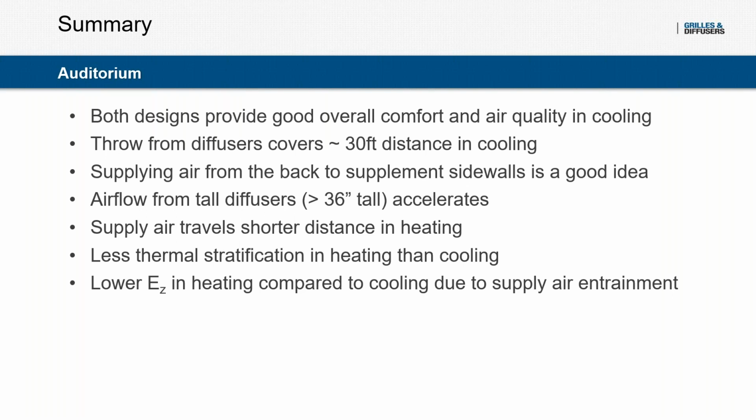We're also seeing that supply air travels a shorter distance in heating. And there's also less thermal stratification and a lower ventilation effectiveness in heating than compared to cooling.